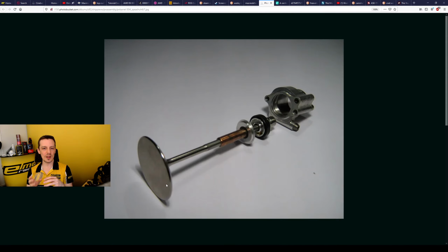So if you're running extremely high exhaust temperatures, like rallycross stuff, where you're running continuous, very high exhaust gas temperatures, then sodium filled stuff will give you higher margins definitely. But that also means that you're transferring heat to the valve guide. So you need to have the clearances for the valve guide correct, and you need to have cooling around the valve guide also, so that it doesn't end up overheating, and all kinds of things need to be taken into consideration. But yeah, those are the material things. Maybe I rambled on a little bit too long about that, but things happen sometimes.